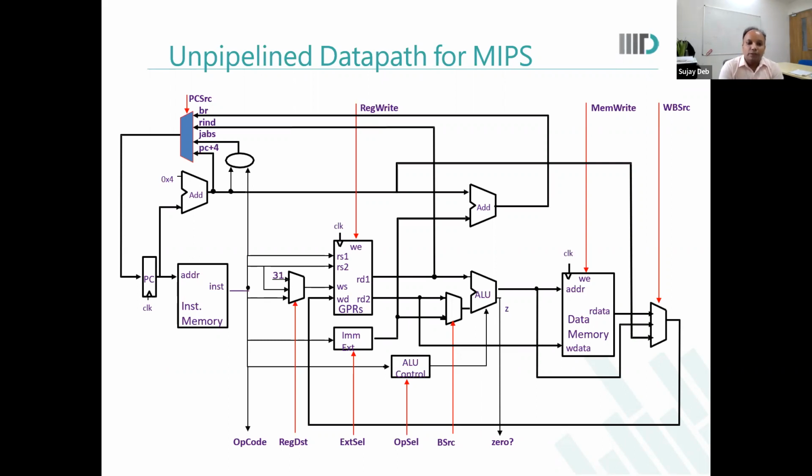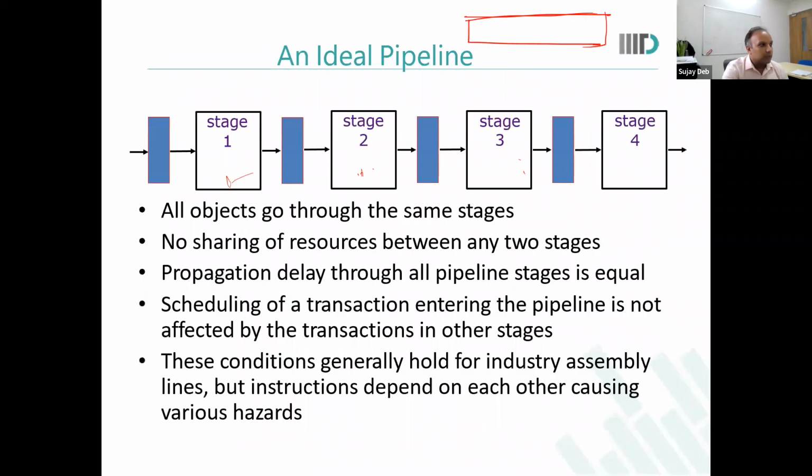So to get to that first instruction, let me go back to the previous slide and explain it. The first stage, let's say, is instruction fetch. So I have to fetch this instruction from my instruction memory. Now, how do I fetch an instruction from instruction memory? I have to have some kind of address to know that this is the instruction which I need to fetch. Generally, this address is stored in a register called program counter, PC.